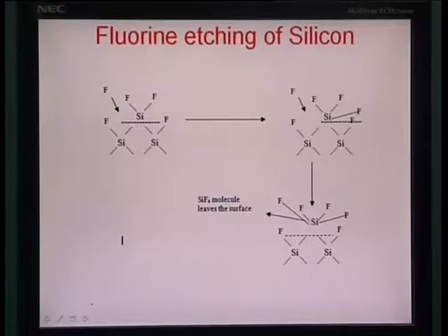Chemical dry etching is also completely isotropic in nature. The technique is similar to wet etching, and exhibits relatively high selectivity, because it is a chemical removal process, and the chemistry is the determining factor. So, if you use a different chemistry which is unsuitable for etching, it can act as an etch stop layer very accurately. Well, that is what dry etching is about.